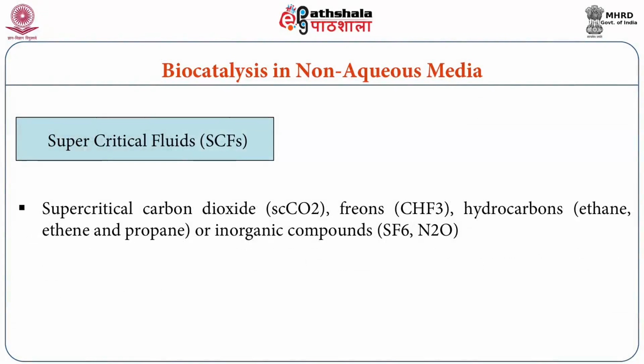Another media is the supercritical fluids. In recent years, enzyme catalyzed processes have been explored in novel media such as supercritical fluids as well as ionic liquids. A supercritical fluid is defined as the physical state of a compound or element above its critical temperature and critical pressure, but below the pressure required to condense it to a solid.